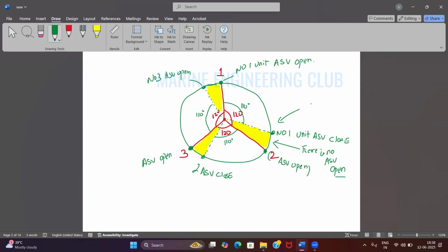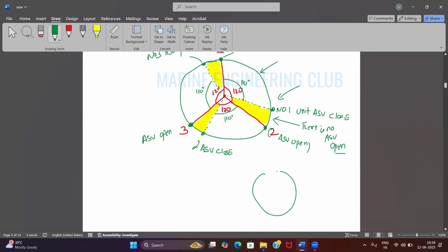So I can consider this as my flywheel, suppose. These are the degrees on the flywheel. Suppose my flywheel has stopped in a region. You have seen the flywheel, it has all of this given over there: 10 degree, number 1 TDC, number 2 TDC, all these markings. Suppose there's a pointer over here on the flywheel, and this region is coming exactly in this shaded region.